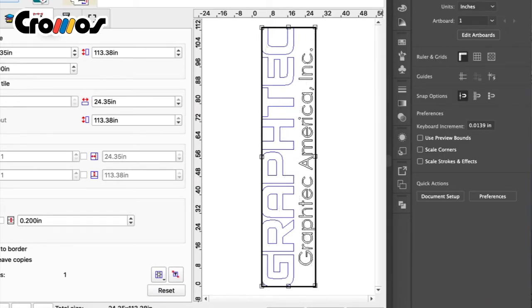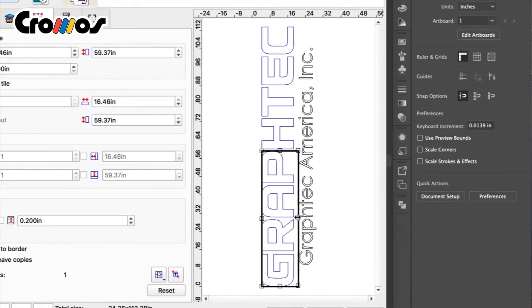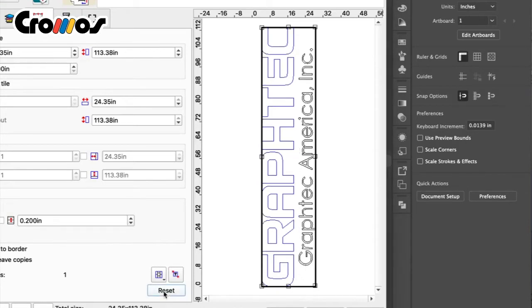and that everything in the black rectangle will be cut. But if we were to grab the top and drag it down, we can resize the panel to exactly what we want to cut. In other words, if we were to cut this job design now, it would cut everything within the black outline or panel and nothing else. This is helpful when we only need a certain portion of the design to be cut. Let's click the Reset button to return to the original panel.